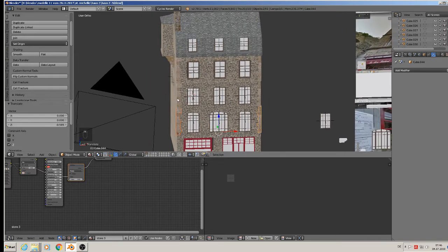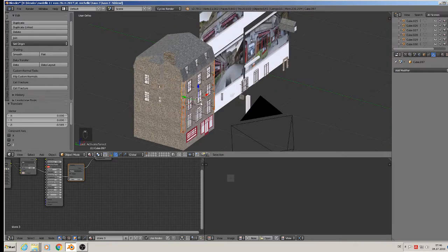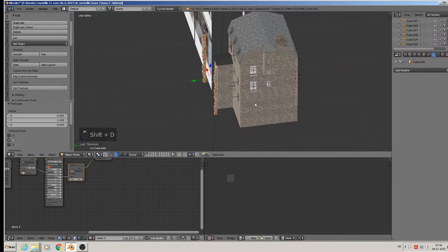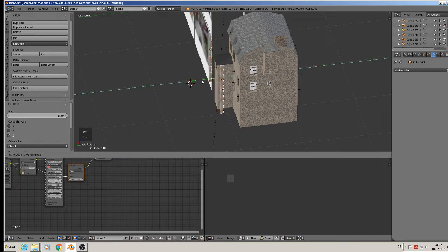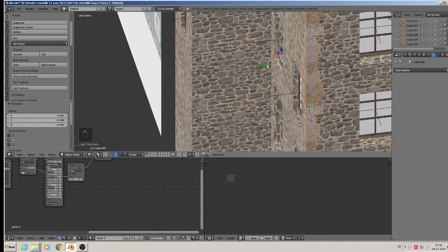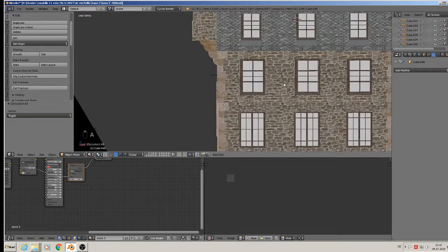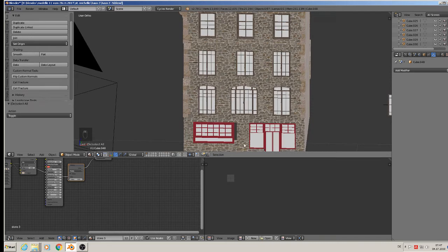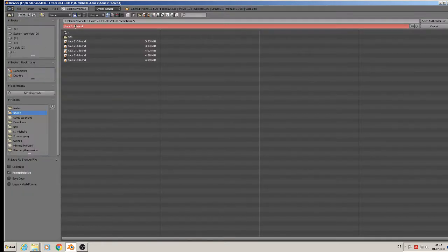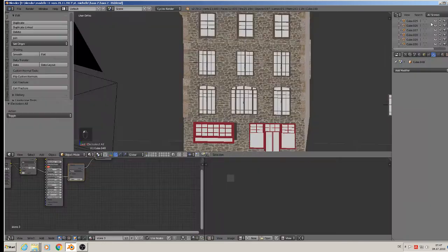So now we take all of them and Shift D, copy, bring it there, rotate set 180 and plug it onto. Good. That was that. That looks much more interesting. Here comes a complete other thing in. So file, save, and save as new version number. We take the 10. Good. Save.